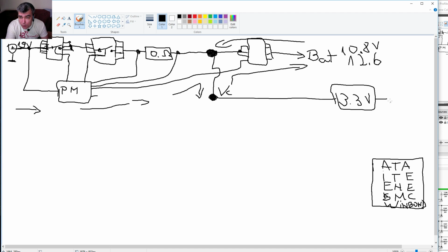This chip is always on 3.3 volts, yeah? That's a controller. That cannot be faulty. Maybe it's erased, maybe there's an error in the program, but I didn't find a faulty BIOS chip. But yes, the program from the BIOS can be corrupt. And also we have the BIOS chip, which is also at 3.3 volts here, yeah.